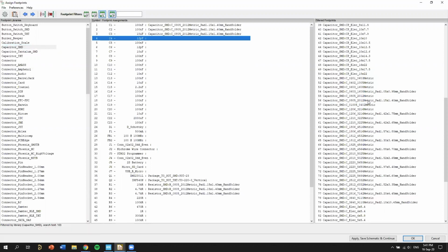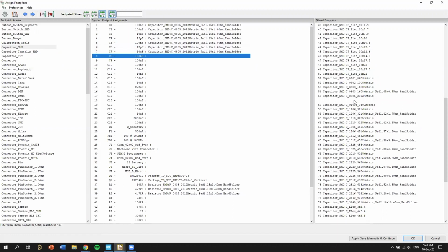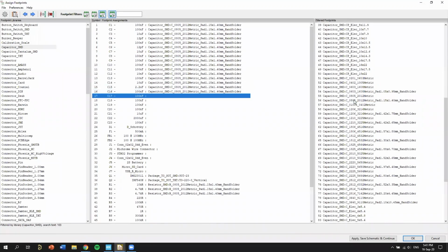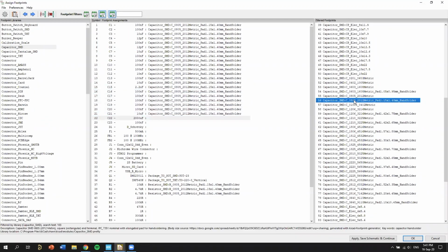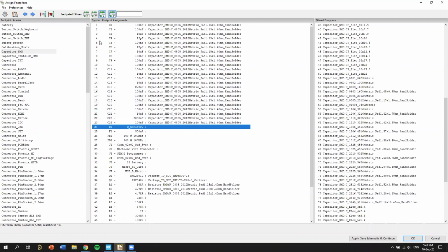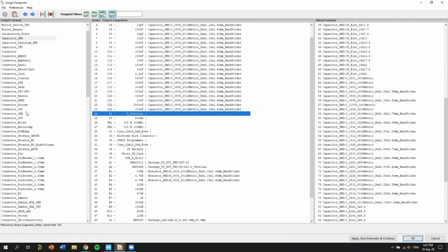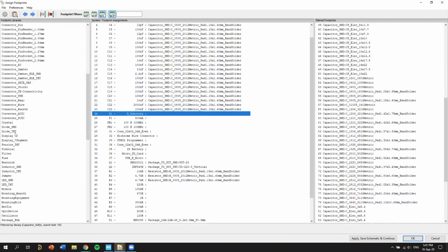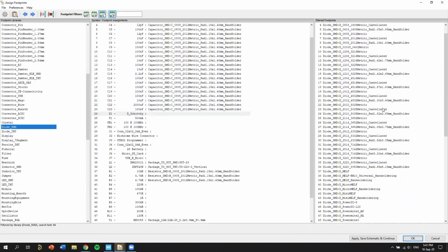I'm going to choose hand solder. Oh, and the picofarad ones, actually not sure. I'm just going to choose hand solder, but JLC PCB are going to solder it for us anyway. It's just if we want to take something off, may as well choose a bigger pad. Cool. Okay, so they're all of our capacitors because they have C's, and we're just going to make them all the same size.